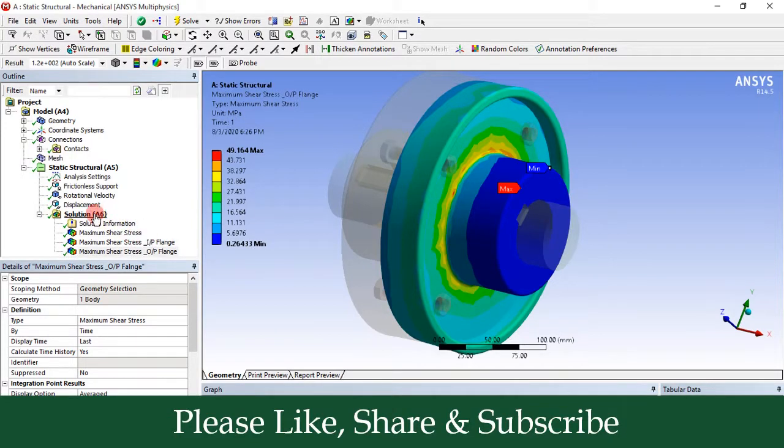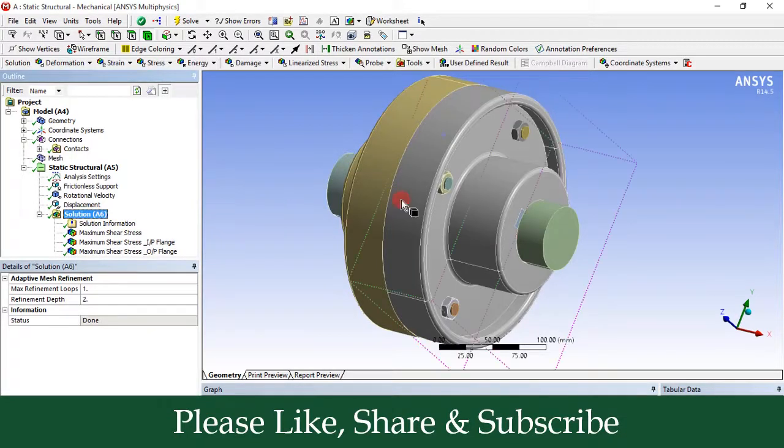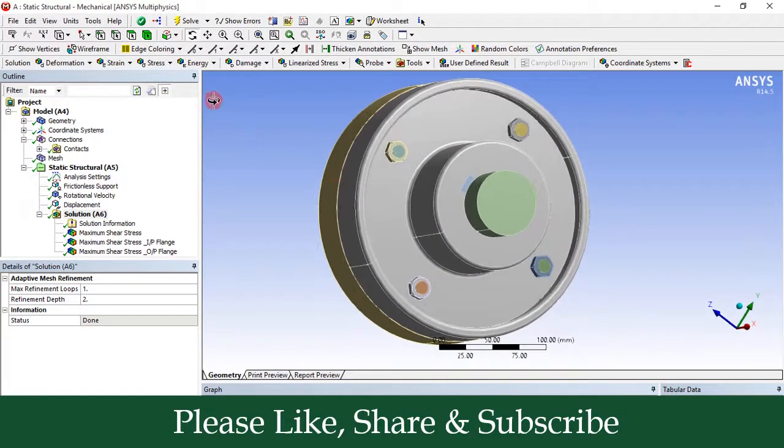Now similarly let us check the shear stress in the bolts. So let us select all the 4 bolts. So again go to this body button, select 4 bolts. By holding the control button you can select all these 4 bolts.